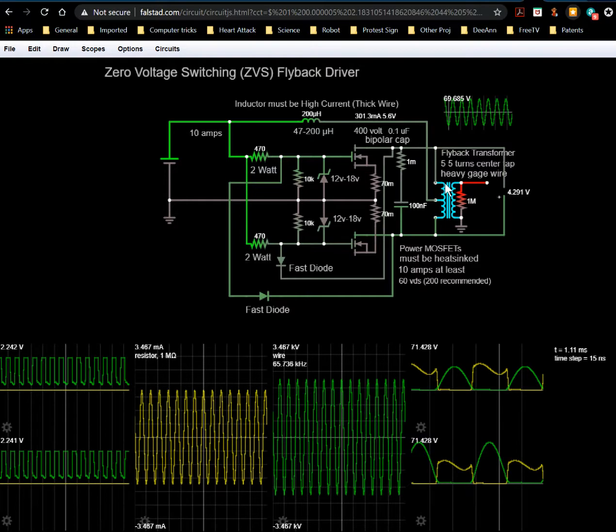But once it's done, you hit the DC state, once that field is fully charged up and it's just acting like an electromagnet powered by a DC battery, there's going to be no voltage coming out of here. It's just going to sit there with nothing. You can't tap into it, because you only get a voltage on the secondary of a transformer when there's a changing current on the primary. But if it's a steady state current, like an electromagnet, you're not getting any voltage out of it. So that's just a little aside on how inductors work if you don't realize it.